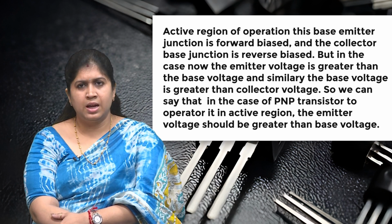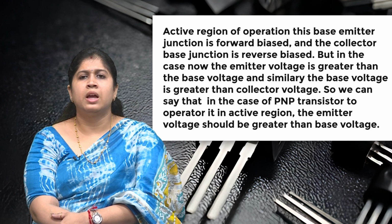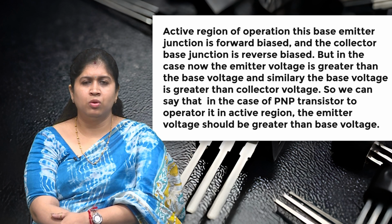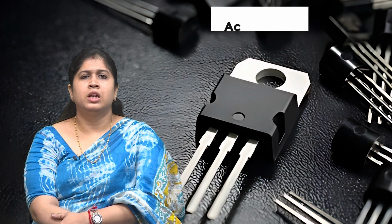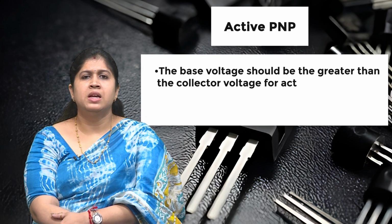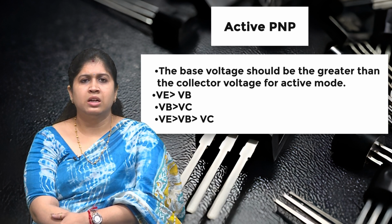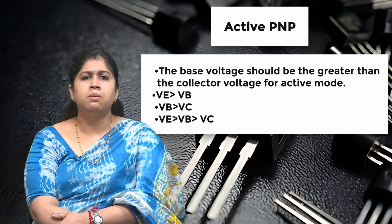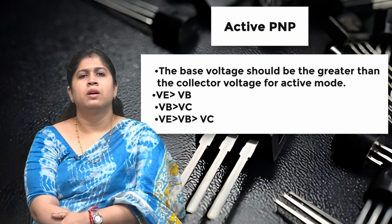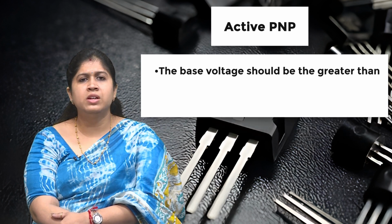So, we can say that in the case of a PNP transistor to operate it in the active region, the emitter voltage should be greater than the base voltage, and the base voltage should be greater than the collector voltage. In the active region, VE is greater than VB and VB is greater than VC, so that VE is greater than VB and greater than VC.